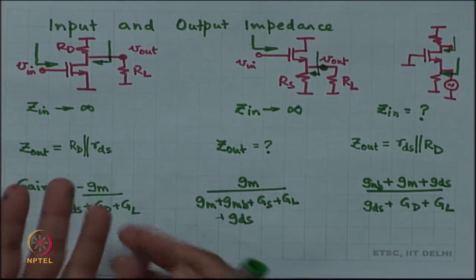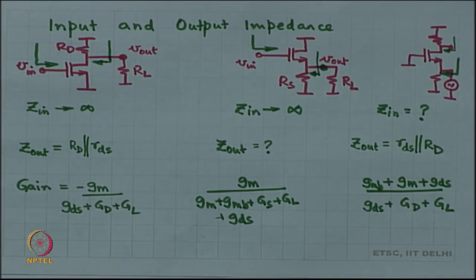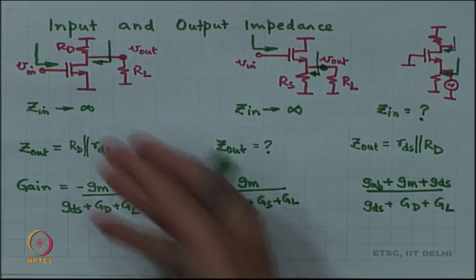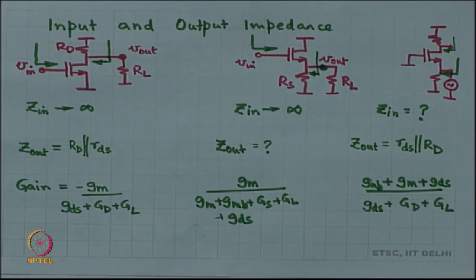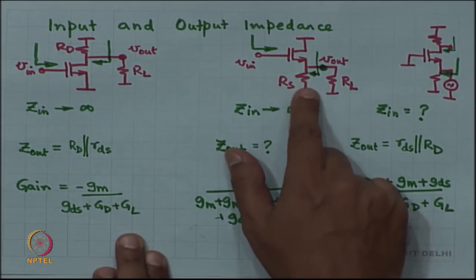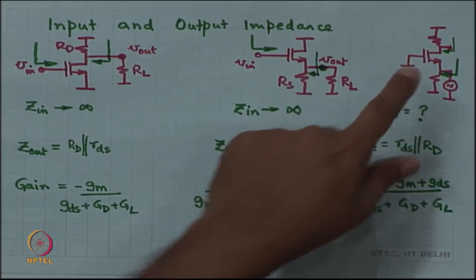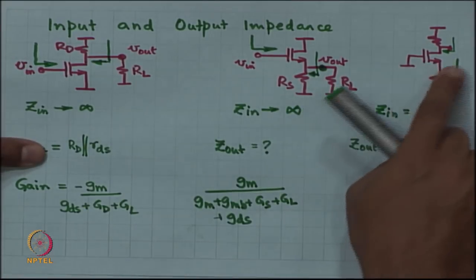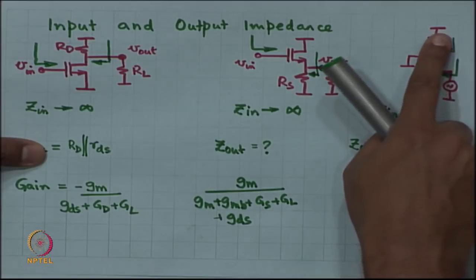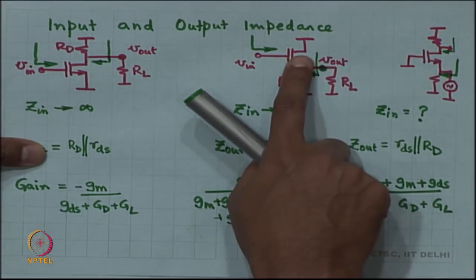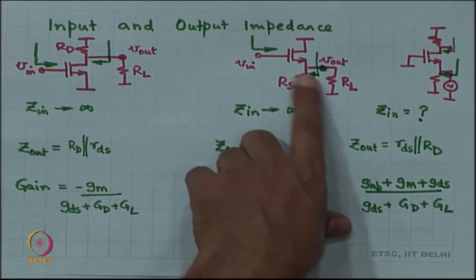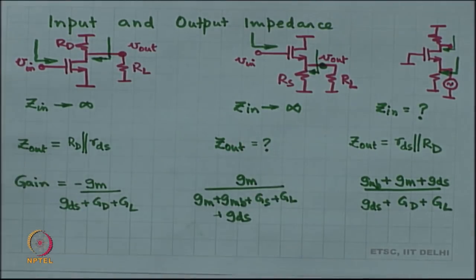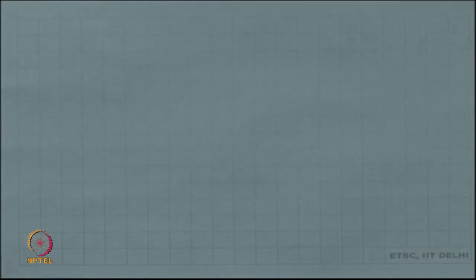Anyway, so you have to work it out, and so these parameters give you an idea of the drive strength, the drive capability of each of these individual amplifiers, and what is needed to drive these amplifiers. So, that is why they are important to us. Okay. Now, we are going to work out these two, this as well as this. I will actually solve this one and then plug in R D equal to 0 and obtain this particular impedance Z out. Okay.